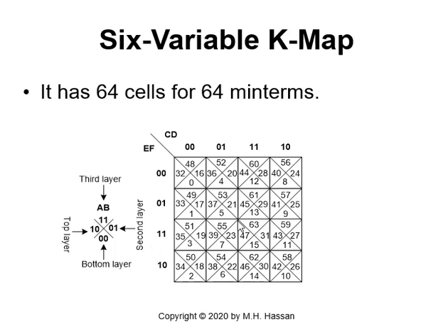Or we can take a 4-variable map, and every cell we divide into four subcells, which is 4 triangles, as you can see here, where this is the key of the AB values. So the AB values will be 0, 0 here, then 0, 1, then 1, 1, and 1, 0. They have to be in cyclic order as well. So the minterm values will be 0, 1, 2, 3, 4, 5, we jump, 6, 7, we jump, 8, 9, 10, 11, then 12, 13, 14, 15, then we start all over again here.